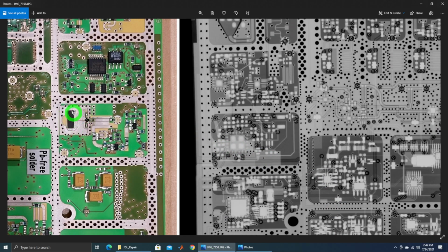It almost looks like a Vivaldi structure, where that feed line couples directly into it and probably excites it differentially. And that gives you an LO differential feed into this mixer. On the other side, it looks like the RF and the IF, I should say, are actually shared with each other. So they're both at very high frequency, so you can couple into it. This is, I think, what's going on. It needs a bit more analysis, but at first look, that's what I believe is going on.